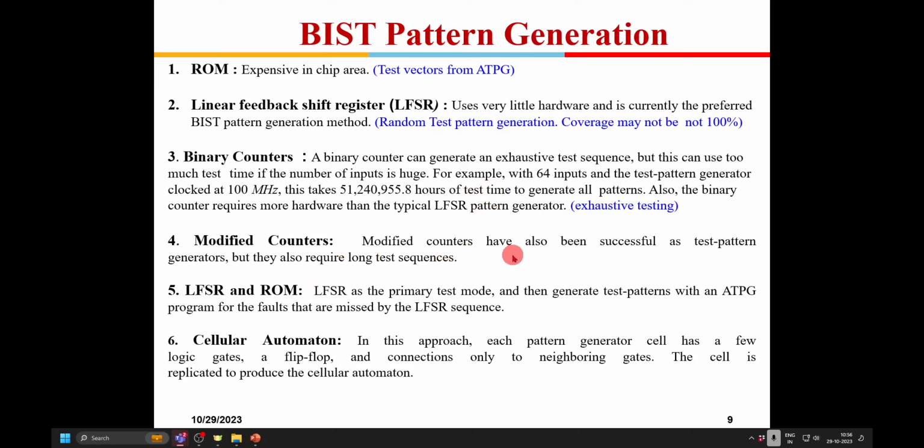Or you could modify the counters also. If you know the test pattern very well, counters can be designed whichever way you want to count. You all have learnt sequential design, where you could have a modulo 3 counter which only counts up to 3 and goes back to 0, or you could have a gray counter. Any counter for that matter, any sequence.